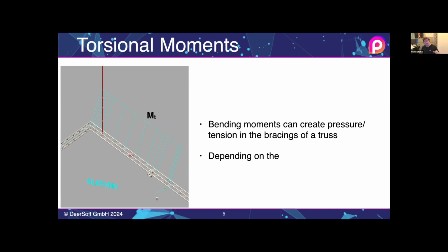Normally, you get the most torsional moments out of outrigged structures, when you outrig something with a pipe. In this case, to make it really visible, I've moved a really big load onto a lever so that you're seeing the torsional moment. The torsional moment will also be shown in light green.